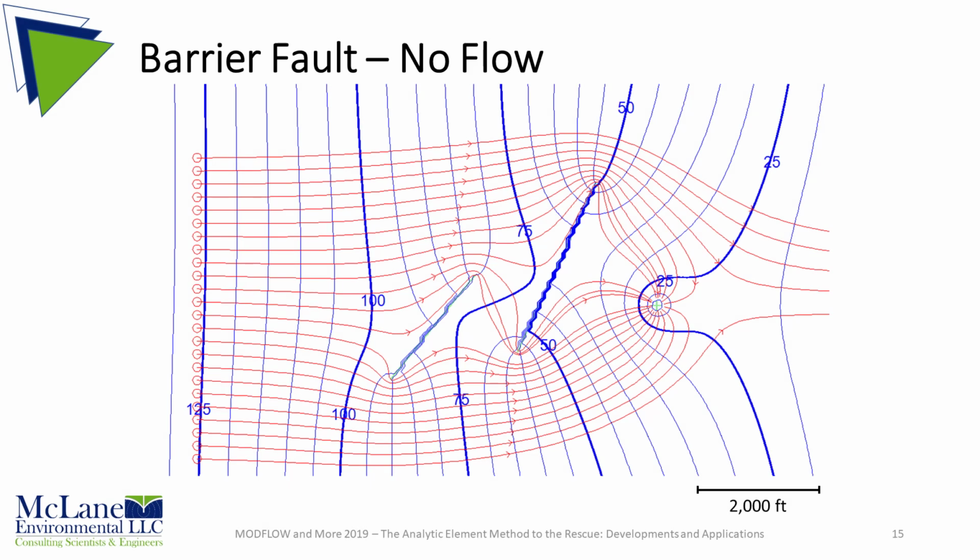In this model, we have set up regional aquifer flow from west to east, or left to right, with a pumping well in the eastern area. Upgradient from the pumping well, there are two sealed faults that act as no-flow barriers to flow. You can see how the flow paths are diverted around these faults. As one example, the purple path line shows that flow from an area directly west of the pumping well is diverted far to the north before flowing around the end of the sealed fault zone and then into the well.